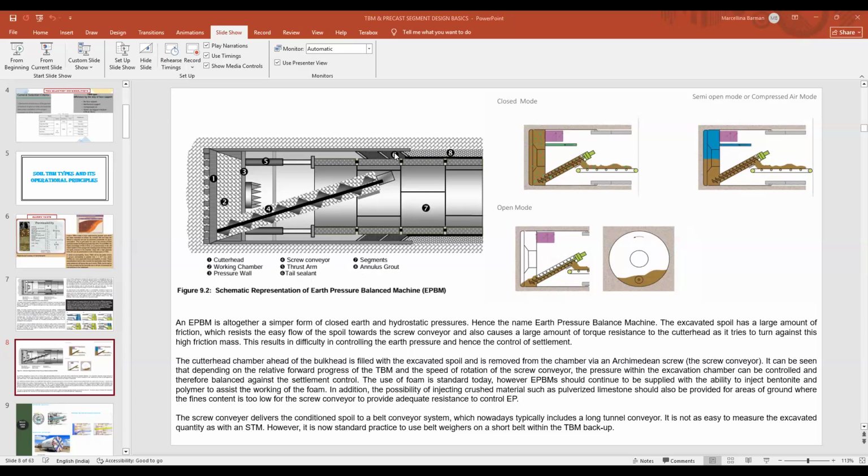It's a very old lake that was hidden inside, and it was directly under very huge residential areas. When the machine hit that part, initially when the water was coming, or when the ground was moving inside the TBM, they closed the working chamber, or they closed the bulkheads. But due to the water pressure, the tail end brush got washed away, and the water pressure became uncontrolled and was entering the TBM. That is why the TBM got stuck for so many months, and overnight 250 to 300 buildings got settled, and the people had to evacuate the buildings immediately.